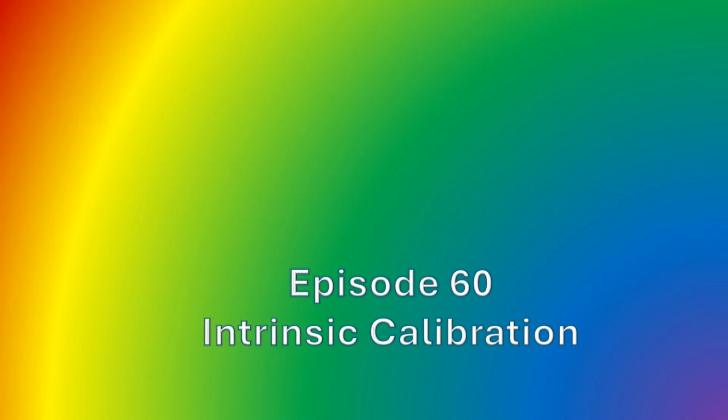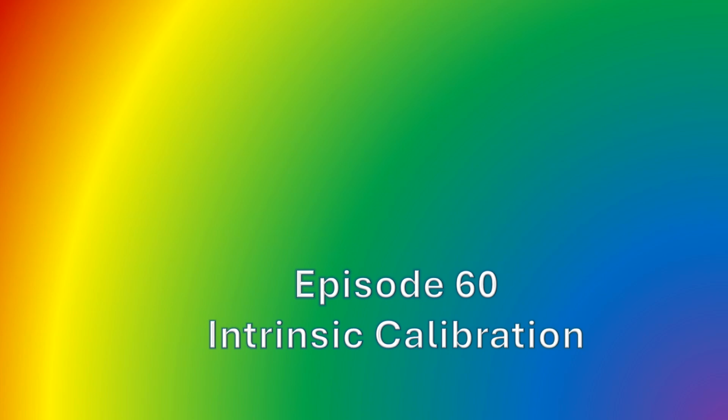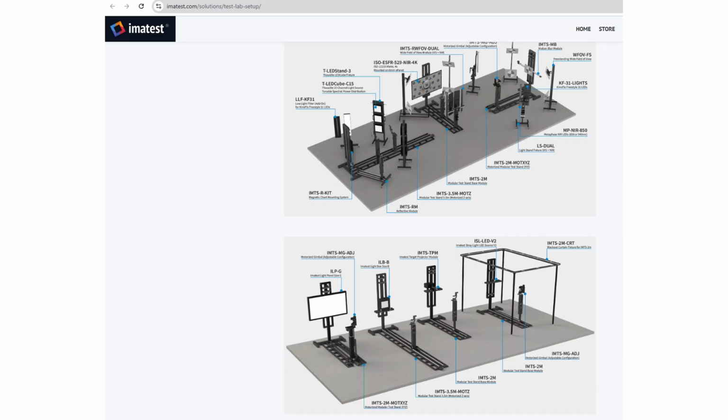Episode 60, Intrinsic Calibration. Camera systems need to be calibrated to understand the forward model of the imaging systems. Intrinsic calibration consists of measuring the internal parameters of a camera, such as its focal length, its principal point, meaning where's the center of the image, and then lens distortion coefficients, and things like barrel and pincushion distortion. Then we have extrinsic calibration, which we'll talk about in the next episode, which relates the camera to the external world. Intrinsic calibration is typically measured in a test lab.